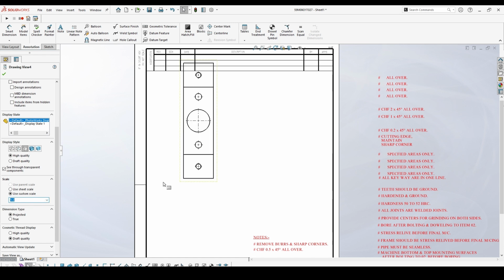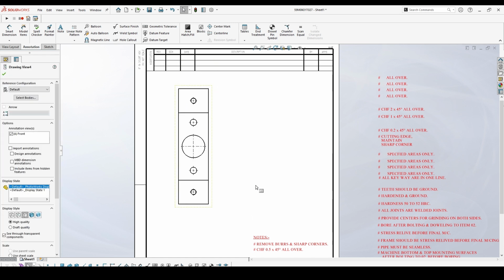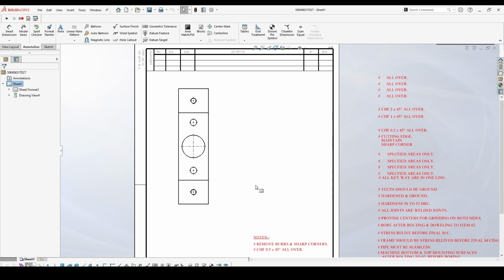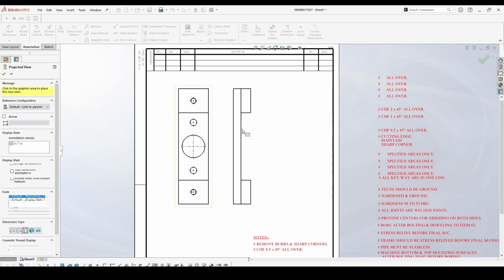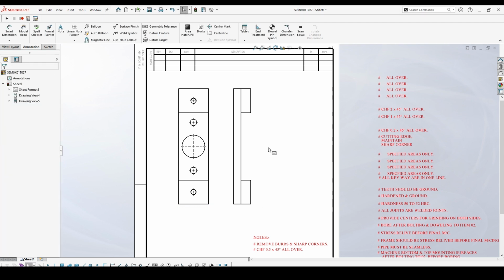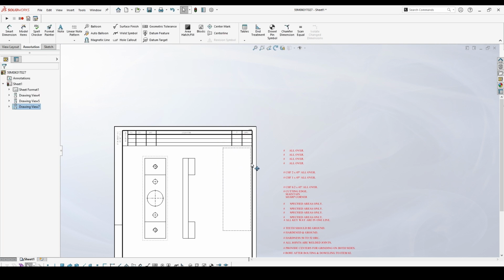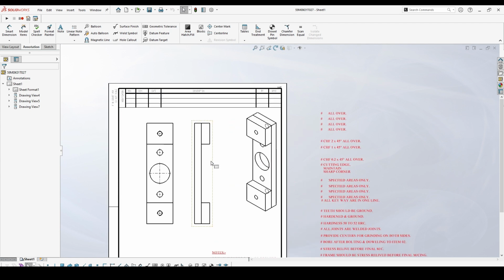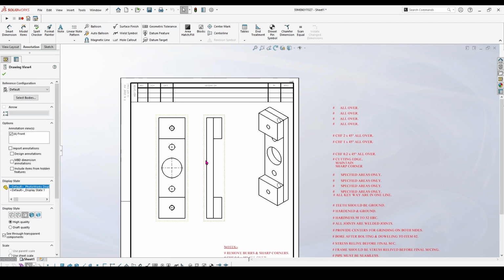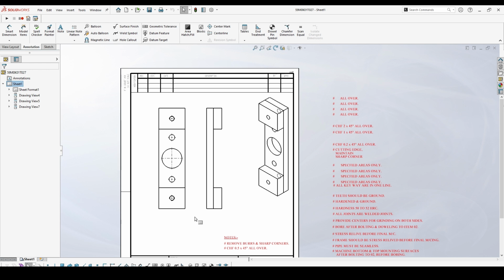Different engineers think different ways, but with my experience, I have spoken to and worked with a lot of machining operators. What I feel is that the drawing should be standard, okay, I agree with you, but it should also be user friendly to the operator who is going to machine it. Nowadays, a lot of people in small industries, small engineering workshops doing job work, don't have proper engineering skill. So we should try to convey the drawing detail in a very simple manner, even putting some dimensions in such a way that he doesn't have to calculate and make a mistake.